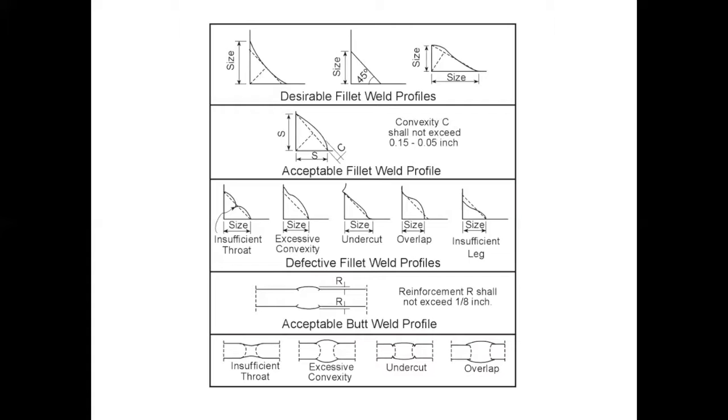The reason for that is if you are welding a pipe and you have a root that's hanging down 1/4 inch the whole way around on the inside, what you're effectively doing is reducing the inside diameter of that pipe by 1/2 inch, because you're 1/4 inch on one side, 1/4 inch on the radius. You have to double that to get your diameter. You're effectively reducing that by 1/2 inch the whole way around. So you're creating a restriction inside the pipe for whatever flowing materials are in there.